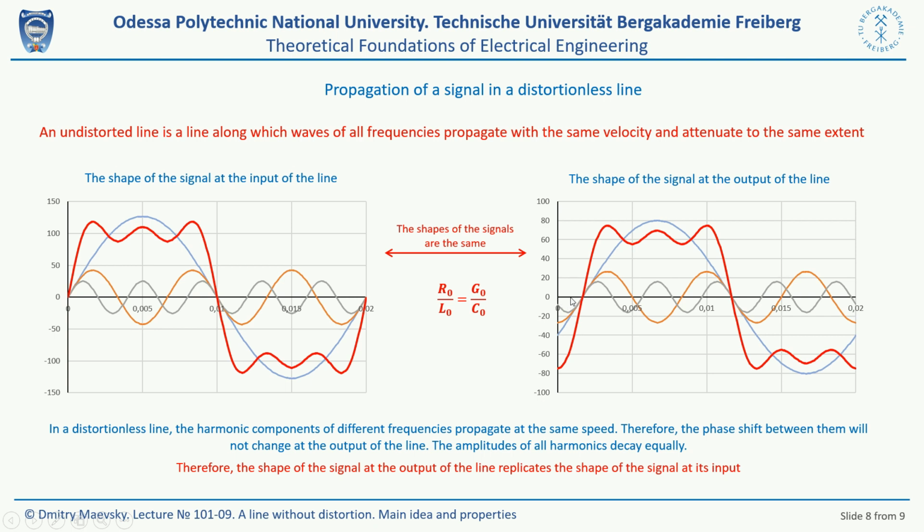during the propagation of all three harmonics along the line, their amplitude decreases, but decreases equally for all harmonics, regardless of their frequency. A phase shift also occurs. Look at the beginning of the line, this figure. All harmonics had zero value, or zero phases, at t equals 0.